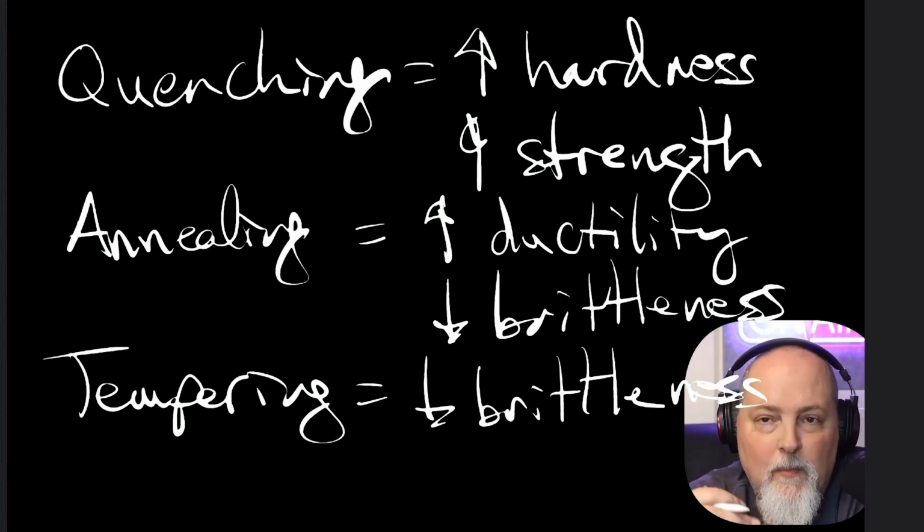And so things that we do in order to minimize that stress caused by welding, the welding stress, we preheat. We do after welding heat treatment. Controlled cooling. We make sure we're using the right weld designs. Stress relief annealing. You don't need to know a lot of those things.